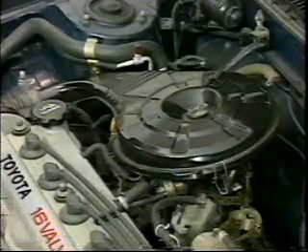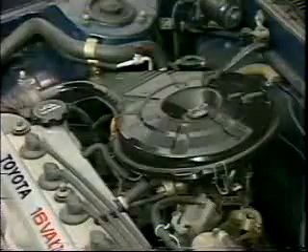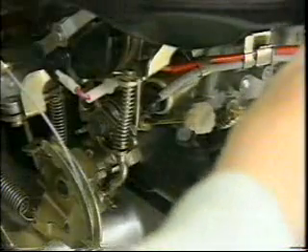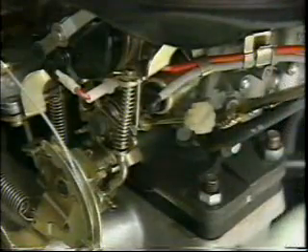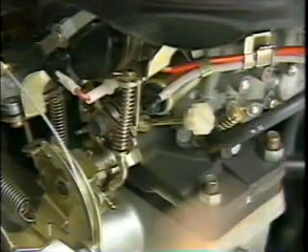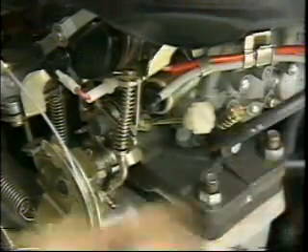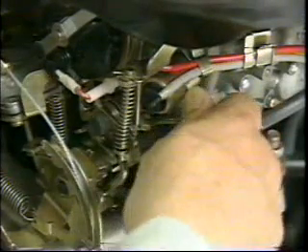In models with an air suction hose to the air cleaner, remove it and plug the end with a hose plug. Turn the idle mixture adjusting screw to raise the engine RPM to its highest permissible idle setting. Then, turn the idle speed adjusting screw to set the idle to the specified idle mixture speed. Repeat these two steps until the engine RPM no longer goes above the highest permissible idle setting. Finally, turn the idle speed adjusting screw to set the idle speed to the specified setting.